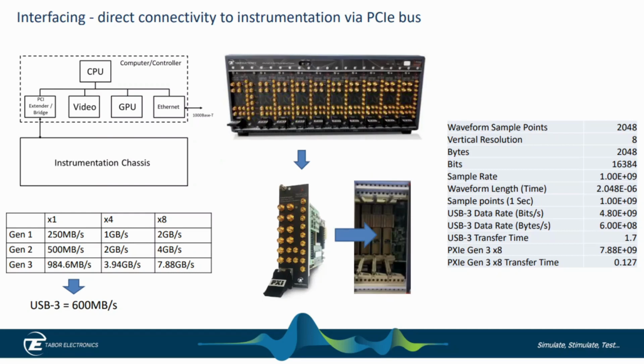To do fast streaming, you need to get data from your computer or your computer's hard drive to the instrument as fast as possible. And the best way to do that is to use the PCI Express format that is within PXIe chassis. So let's look at PCIe.